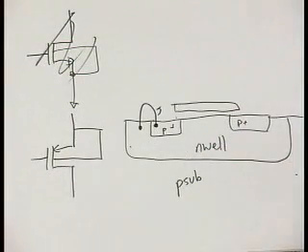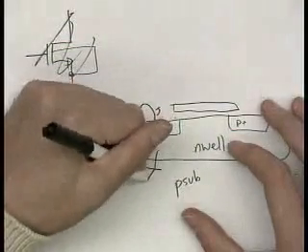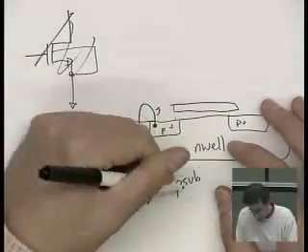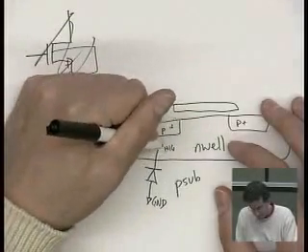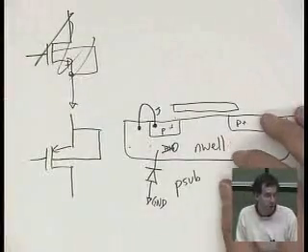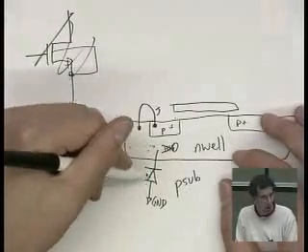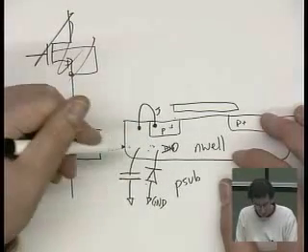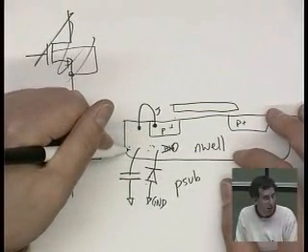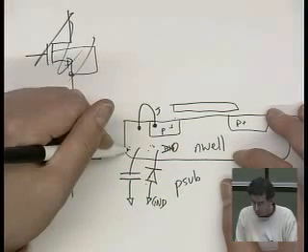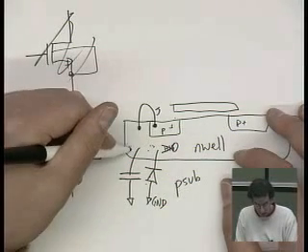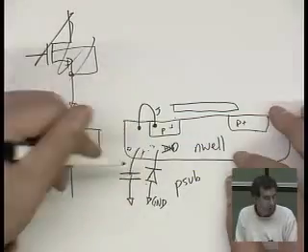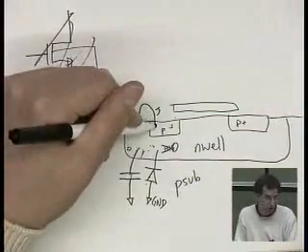Becomes a bigger device. An additional thing that happens is that this P substrate is grounded. So this is grounded, and this is some higher voltage. This voltage is greater than 0. So now you've got a reverse bias diode here, which manifests itself as a depletion capacitance. So now, because this node is not tied to VDD, this node moves. You're modulating this capacitor, and that means that you've got an extra capacitor effectively on the source node. And Saurabh shows it right here in this handout that he put together.